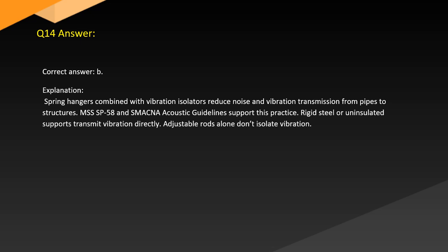Answer. Correct answer: B. Explanation: Spring hangers combined with vibration isolators reduce noise and vibration transmission from pipes to structures. SMACNA acoustic guidelines support this practice. Rigid steel or uninsulated supports transmit vibration directly. Adjustable rods alone don't isolate vibration.